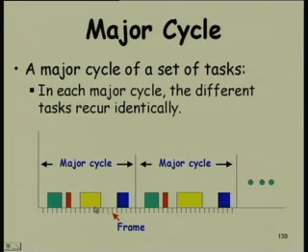So, some time may be wasted, nothing is running here, because the task started at a frame, but could use only a few frames and part of one frame. This much is wasted, but in a table driven scheduler, as soon as this completes, we could have started another one. So, that way possibly it uses the processor time less efficiently, but it has a major advantage, no timer setting is necessary.